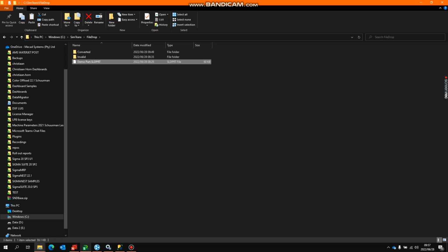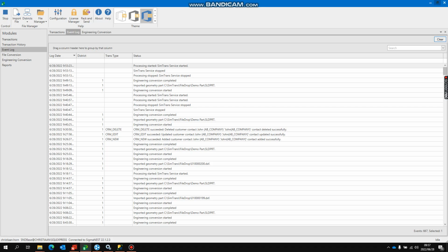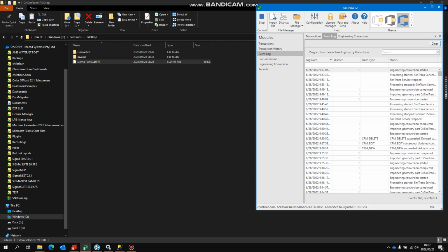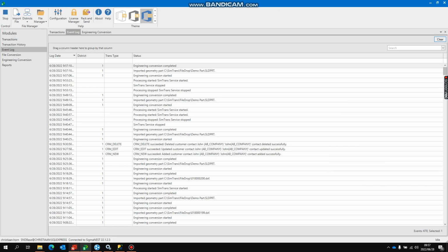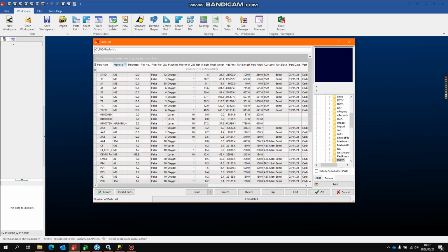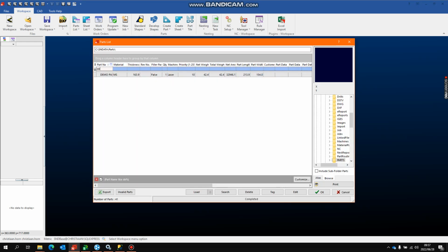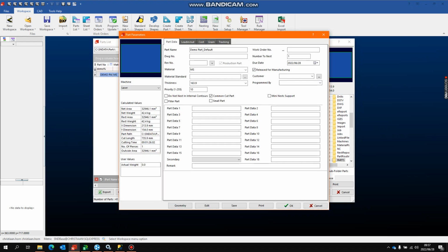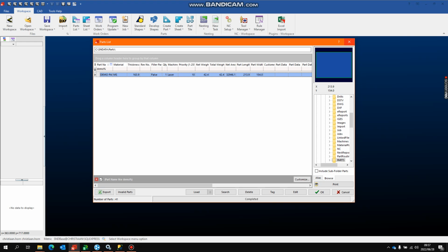You will then see, once I open SimTrans here on the side, it will say processing started, that file will disappear, there it goes, and engineering conversion has been completed. If I go now to look for that demo part within SigmaNEST, you will see that it's already there, created, and I can just go nest it and post it. I can always obviously edit it and change or add any information needed beforehand. That's one part of looking at it.